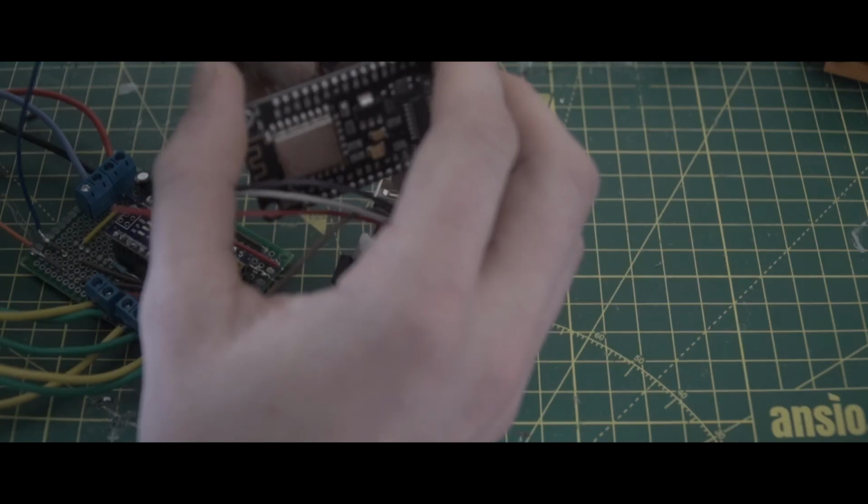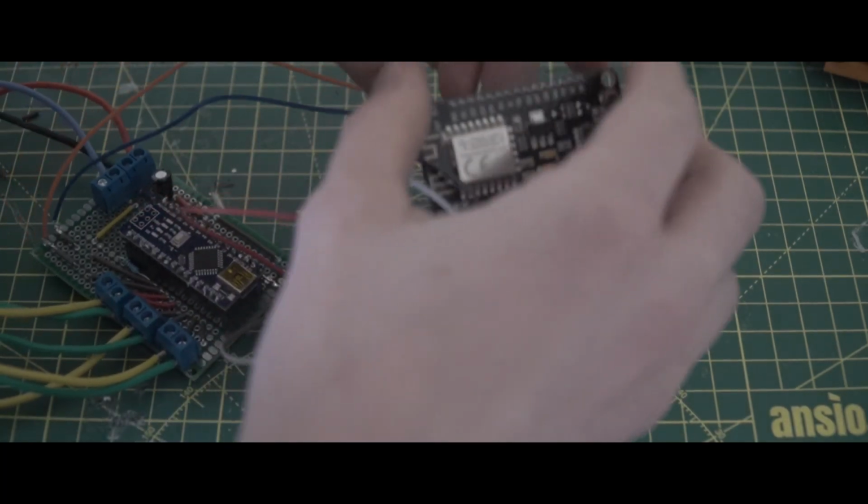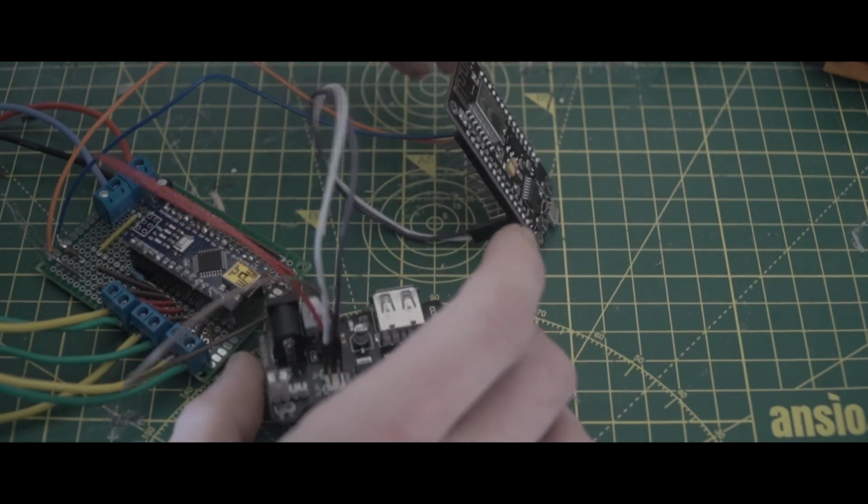Digital pins 3 and 4 are used as serial receive and transmit pins for communication between the Arduino and the Node MCU. This works pretty well, however, because I'm using the Arduino software serial functionality to reassign these pins as serial I/O, I am noticing a small amount of interrupt that's affecting how smooth the code runs. It's subtle, but it's noticeable, so I'm currently exploring a couple of different approaches that will hopefully fix the issue.